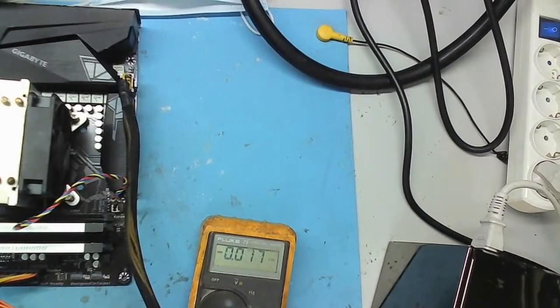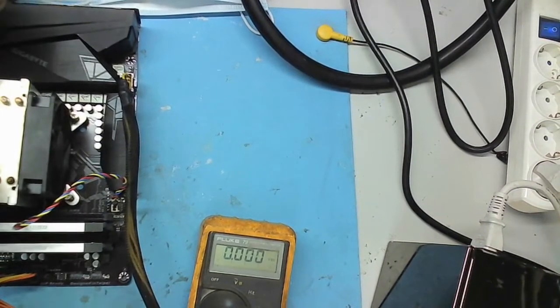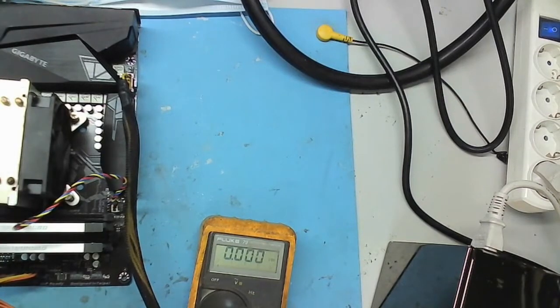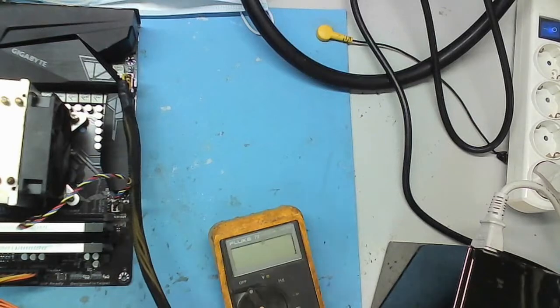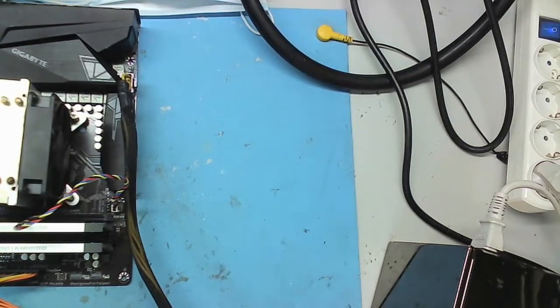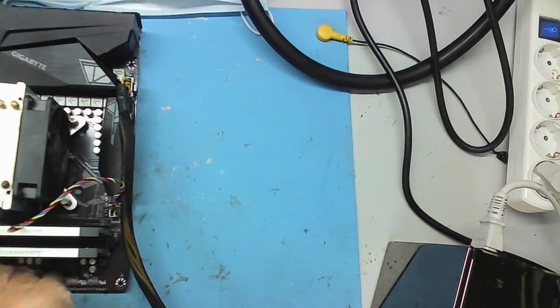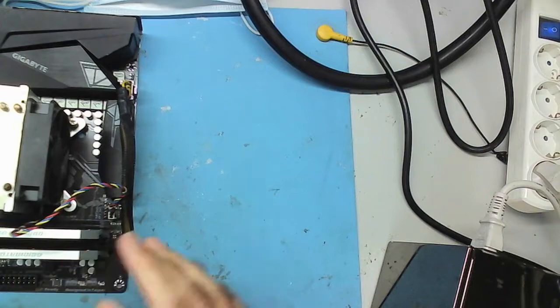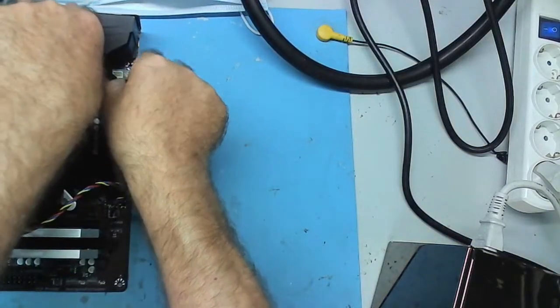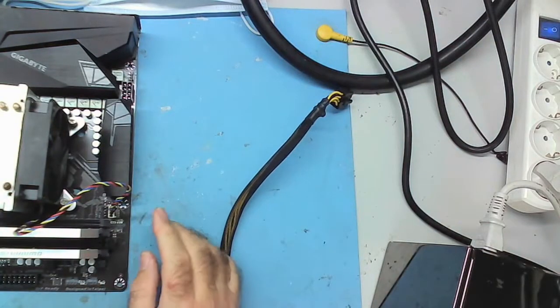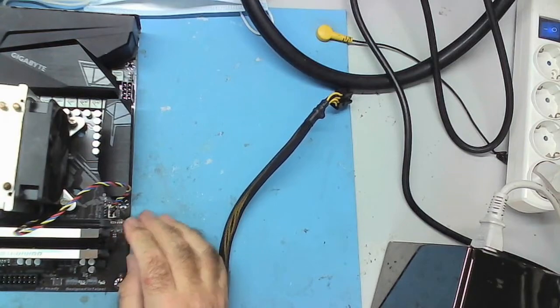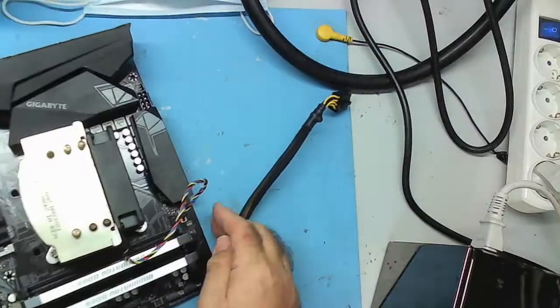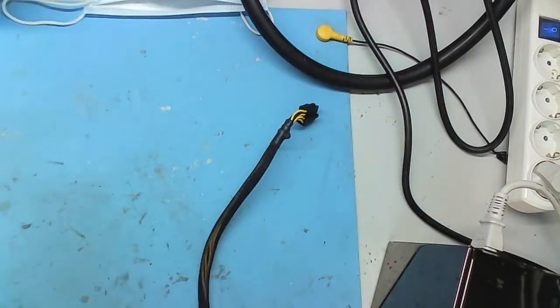That's interesting. We found the fault on the other one. Standby voltage is way too low. Way too low. Let's see if we can figure out why. So this one, we know it powers on but doesn't do anything. I suspect there's no power to the CPU because it's not getting warm at all. This is getting warm. We need to investigate that. But let's put this one on one side safe for a moment. Just give me a moment.